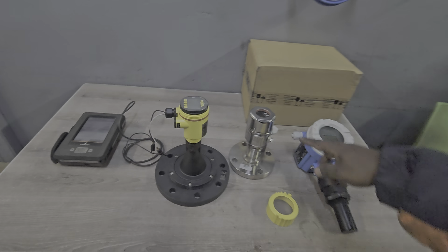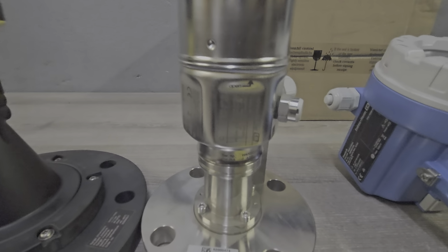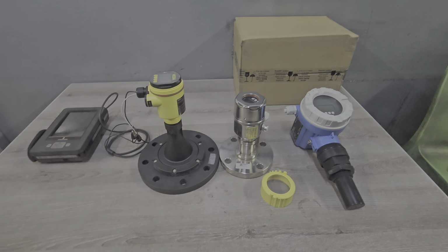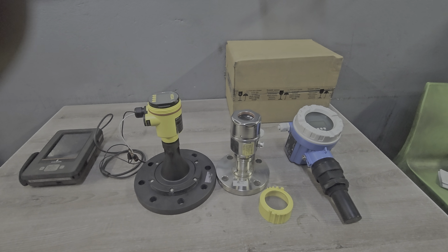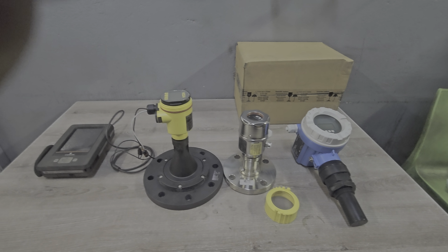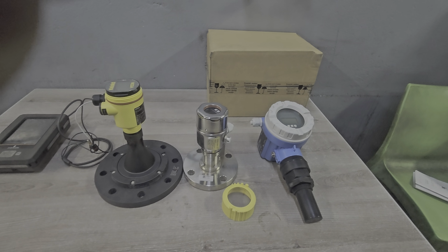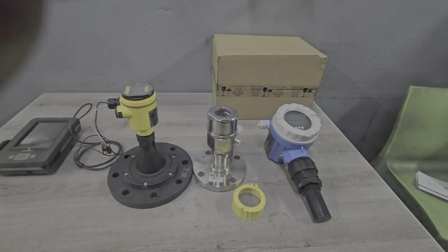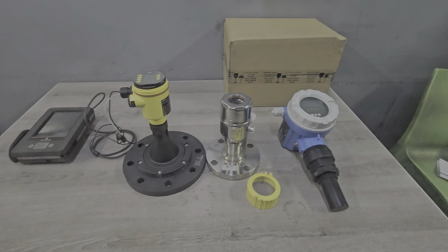Okay, I think I've already explained enough about the Vegabar. This one is also manufactured by Endress+Hauser. If you come closer, there are the specs. The specs explain the minimum pressure, maximum pressure, the type of current that you can apply to it, and the temperature and process environment that you can use it in. If you look at both of them, one is more like plastic, and the other is metal. So if you are dealing with high temperatures, maybe this instrument might not be suitable, and you might want to use this one, but you will consult the technical documentation.